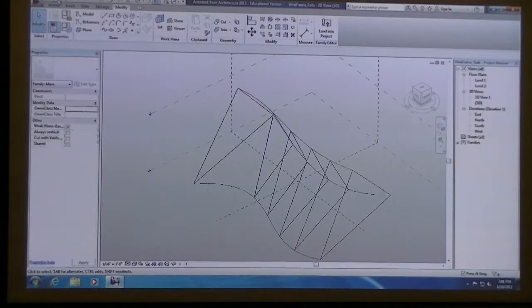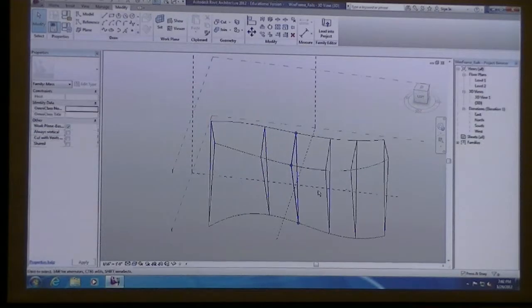What this is doing is it's allowing you to, some of you might have some complex curves. Well, we all have complex curves, but what I'm thinking is a lot of you are having some lofting problems from one curve to the other when we're just selecting curves from the endpoints. But if you have a series of section curves that might be associated with those original rails that you've already developed, you could try lofting the section curves from this adaptive component.